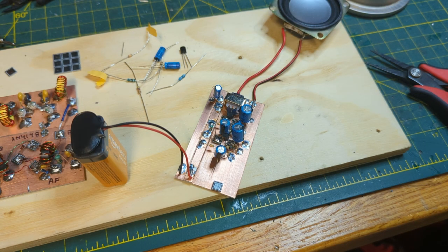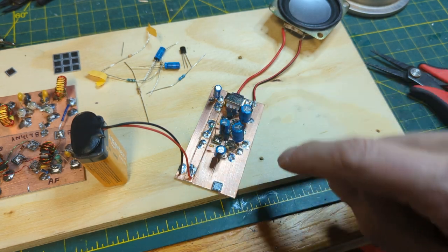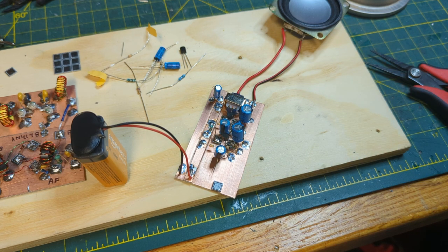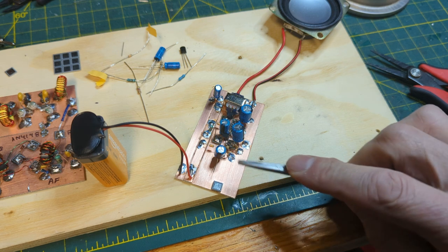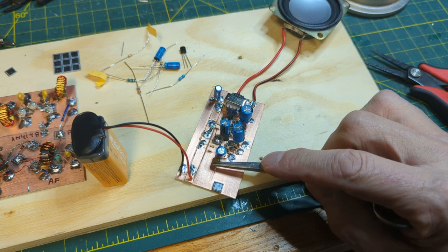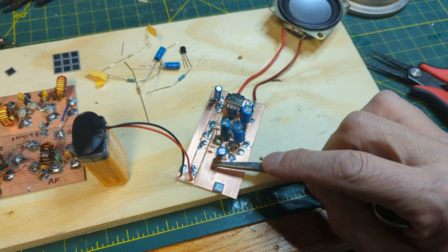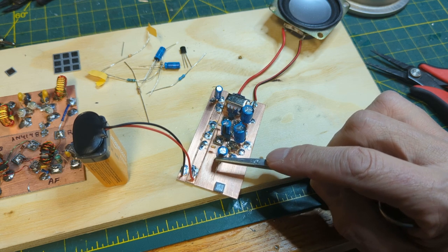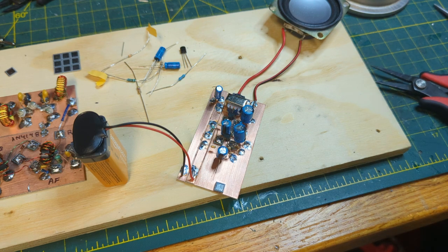We have completed the Q3 build, so the next transistor is in. And now that we have 2 stages in there, I think we'll find that when we touch the input, we're going to get a nice little noise on the speaker. There it is. So the 2 stages are in and amplifying. And we got a nice loud hiss, so we've got 2 stages of amplification in. Next step is going to be to put in the potentiometer, and then we will see from there.